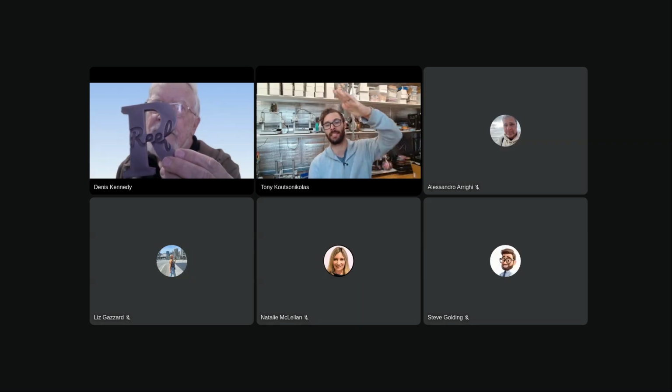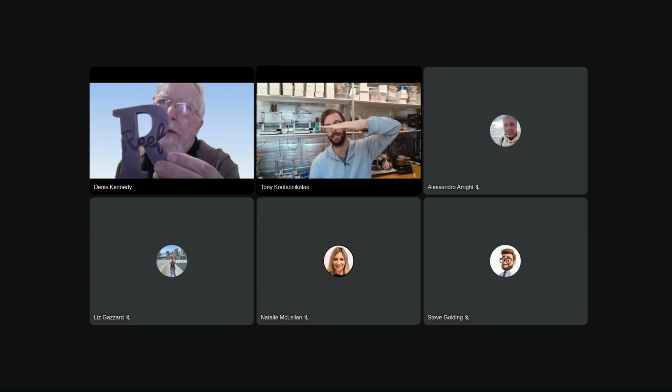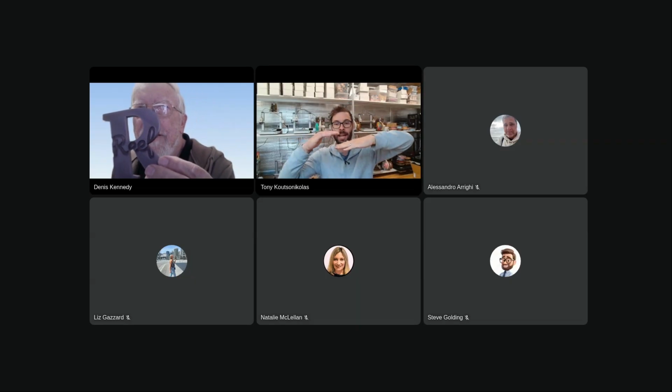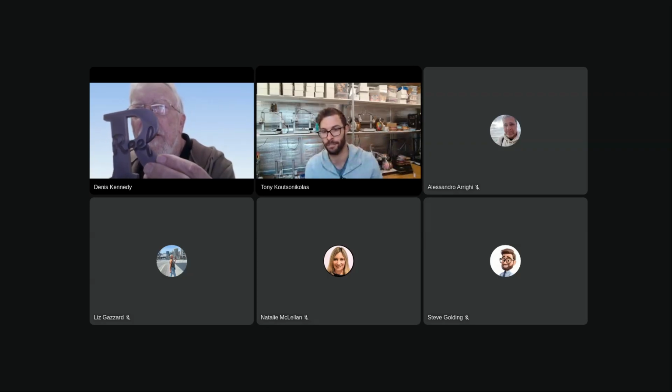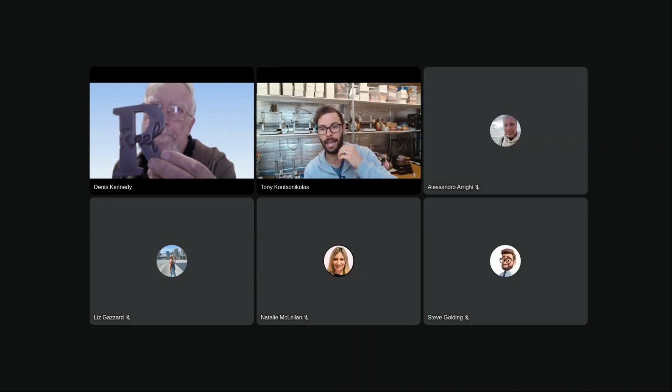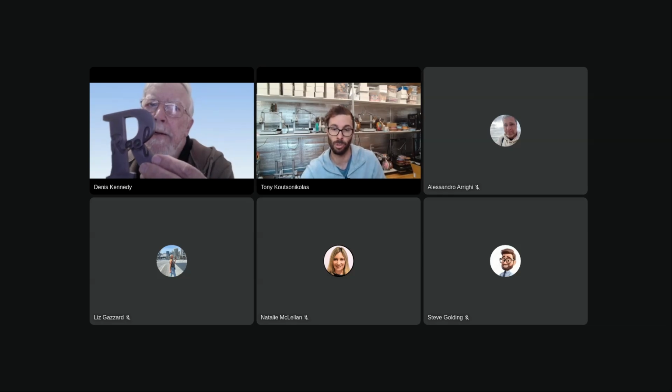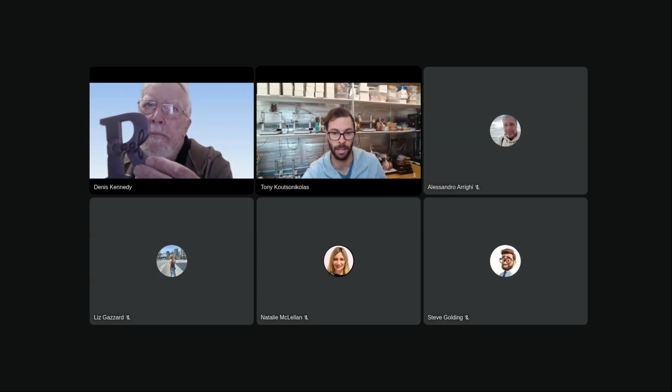So you're probably printing that so the R is flat, right? On that top surface, that texture is going to have a really hard time to actually pick up because it's not going to have enough layers to create the nice effect that you're after. But I think you want to exclude that cutout region. Is that what you're saying? Yeah. So in BumpMesh, use that exclude tool, and it would be really easy to exclude it from that little cutout because you can use the fill detect. Hang on, let me show you.